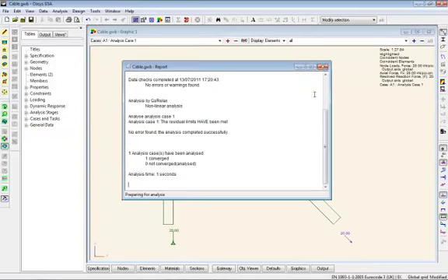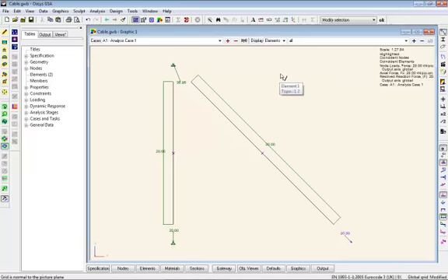If I rerun that, you see with the cables, because the tension is remaining constant, these essentially pass over this node up here, so you get a higher reaction. This node becomes effectively like a pulley. We then get reaction down here. So cables can be very powerful, very useful if you know what you're doing with them, but they have to be used with caution, because the results can be unexpected if you're not careful.